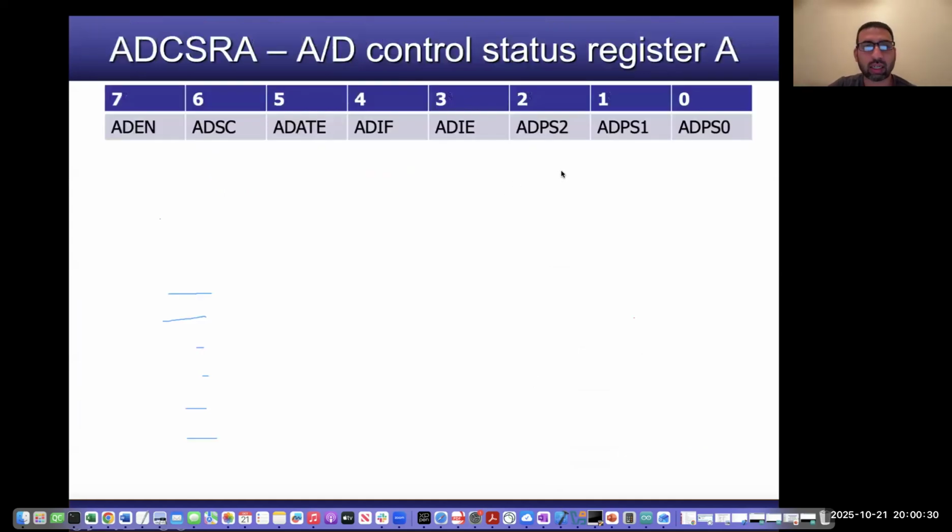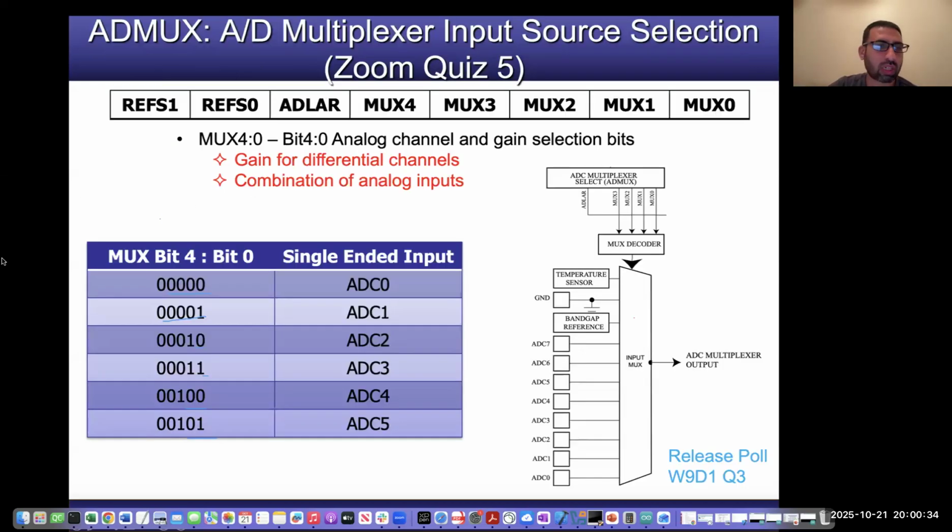So let's have a look at what the value should be. We wanted to use ADC3, like we wanted to select this one as input. So if we look at the table, here I'm starting with 1 1 0 0 0, and we wanted to do the right adjustment, so this will also be 0, and we wanted to use the internal reference voltage.